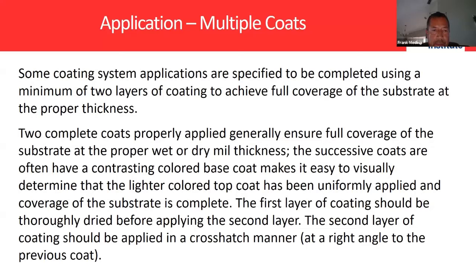We had a full-time Tremco rep on site for us, and he was kind of giving us the blessings of the install process. So we were doing the primer. The primer had a 3 to 4 hour window to cure before we went with the first base coat.